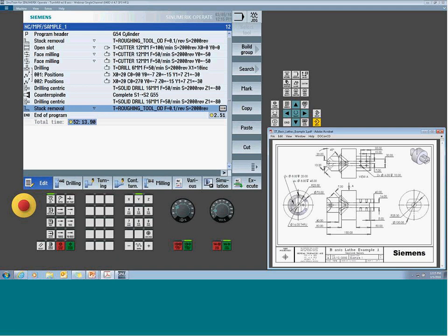That's my shift, 10 mil up. I get 45 degrees about the y-axis, which is why we have a positive 45 in our y. And then if you look, I know the center line of the hole I'm going to put in later is 10 millimeters off of that edge. So that's how I slide my 10 millimeters up in my x-axis.